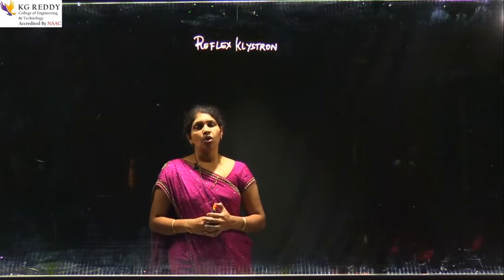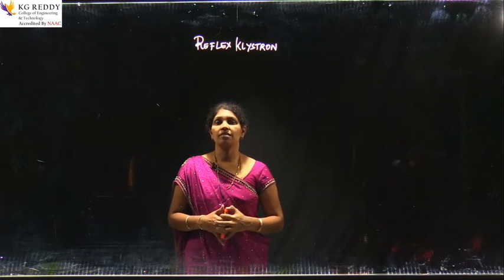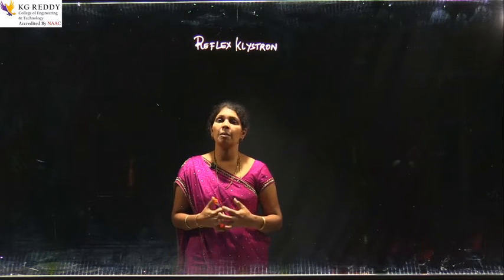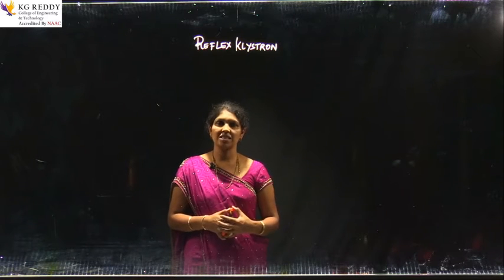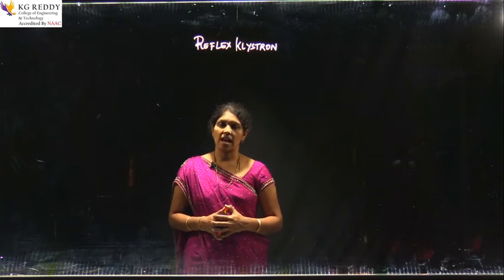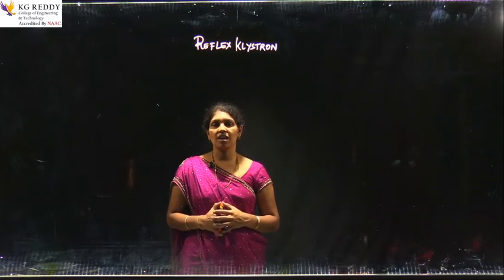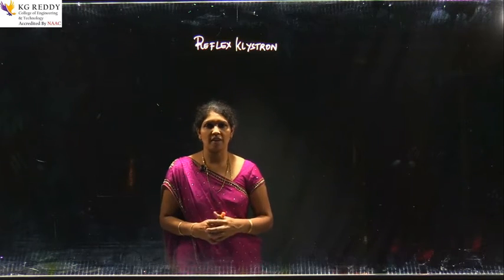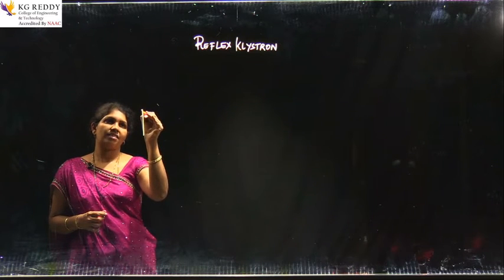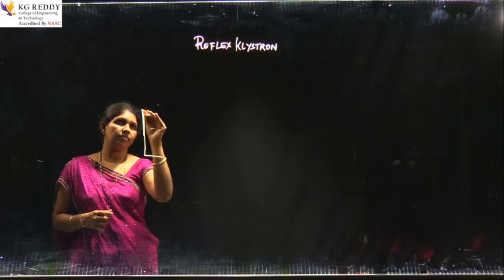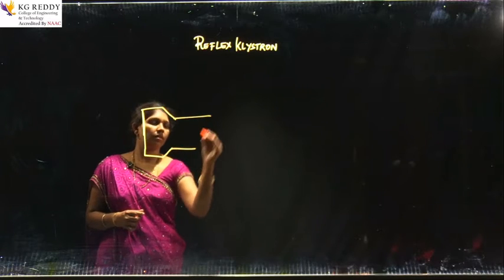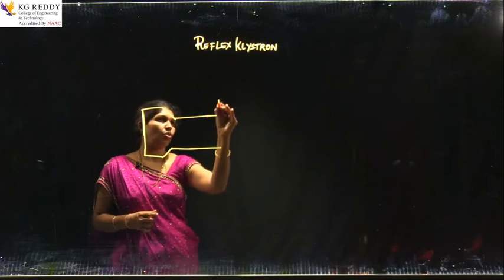Now, we know that two cavity klystrons are better used as amplifiers. When we try to use them as oscillators, we face many problems like phase effect and bunching problem. Hence, we go to reflex klystron. The reflex klystron has only a single cavity, so we can overcome all the problems of two cavity klystron. The reflex klystron also has an electron gun. It has only one cavity.